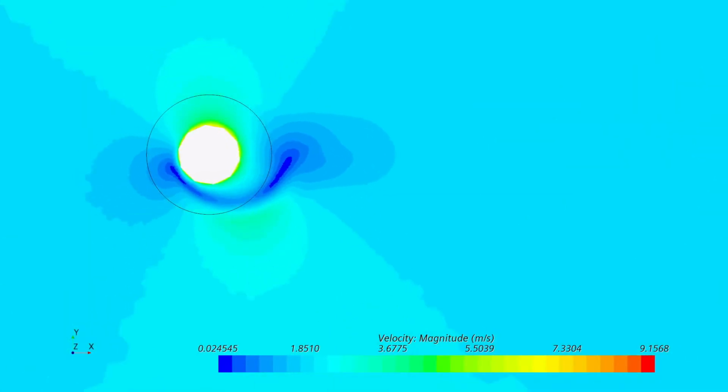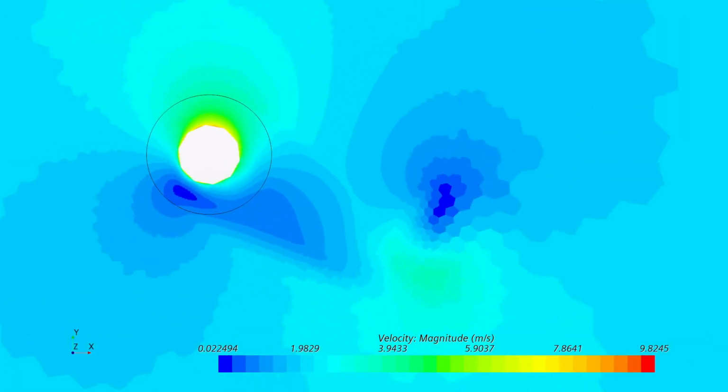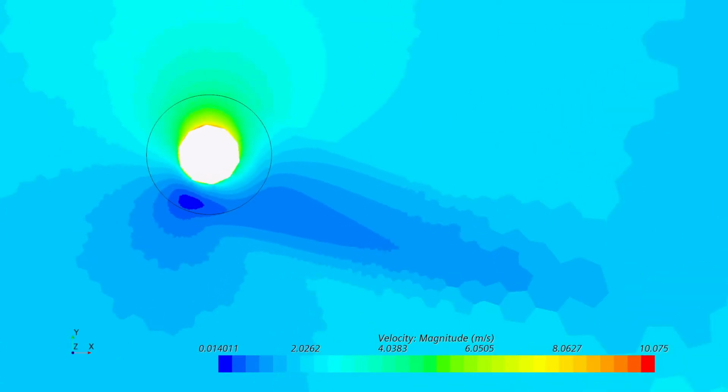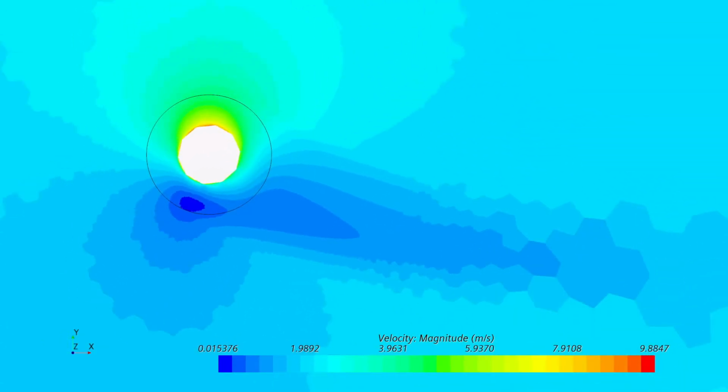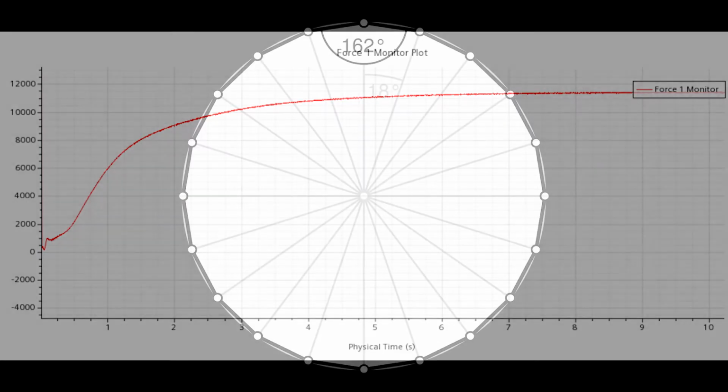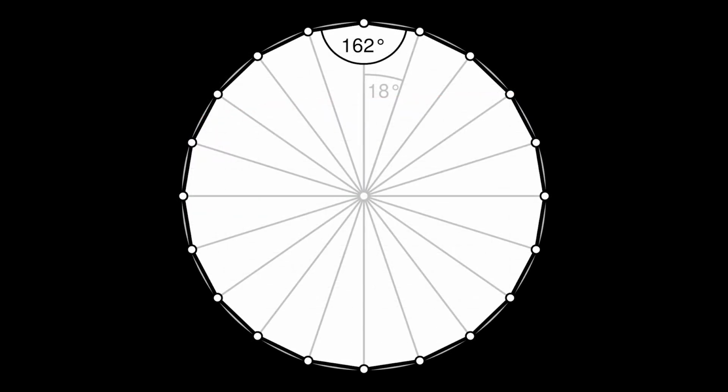The decagon test ran as expected and garnered a lift value of 11,300 newtons. This is only 1.5 times that of the circle, which is lower than what Pezzati describes. As the geometry gets closer to that of a circle, the lift value should end up being similar to it. Further research could be done on n-gons with 20 plus sides to see if there is a point where the circle is effectively no different in lift.